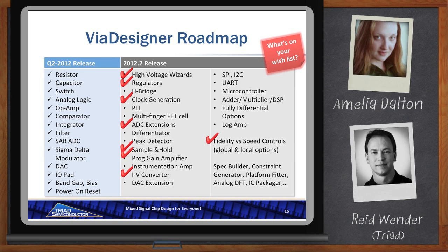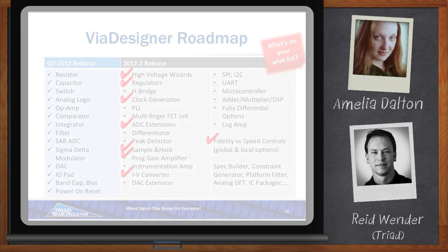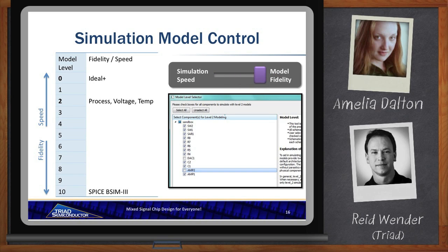It's based on low-level SPICE transistor modeling and simulation. If you were to build a useful system, say maybe op-amps and muxes and filters and an A to D converter, it really can take almost forever for those simulations to complete. And we actually hear engineers complain the simulation won't complete before a core dump. Wow. Designers just don't do system-level analog SPICE simulation.